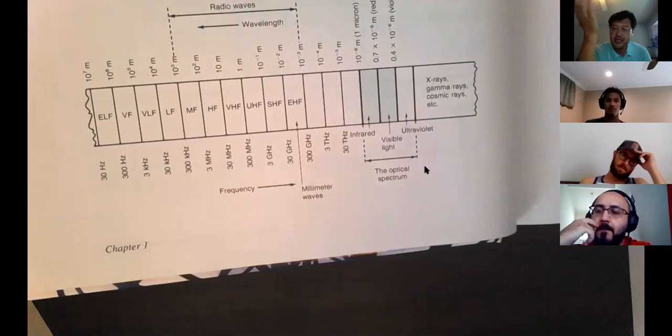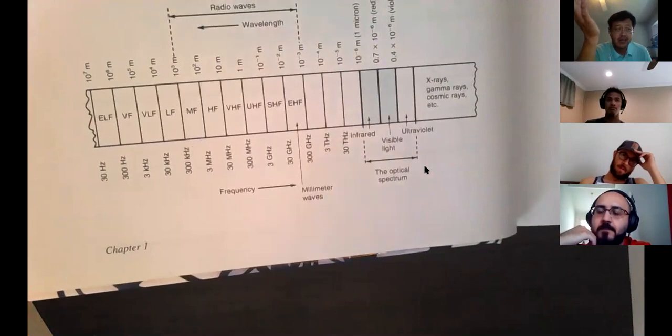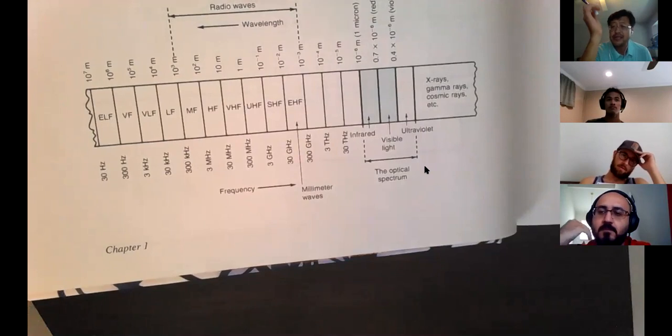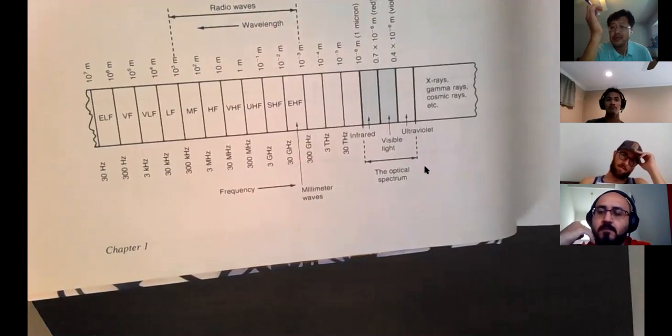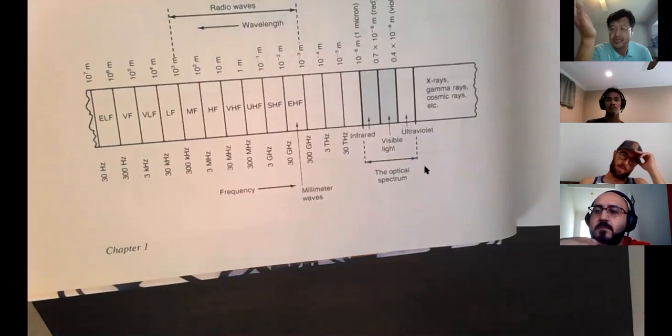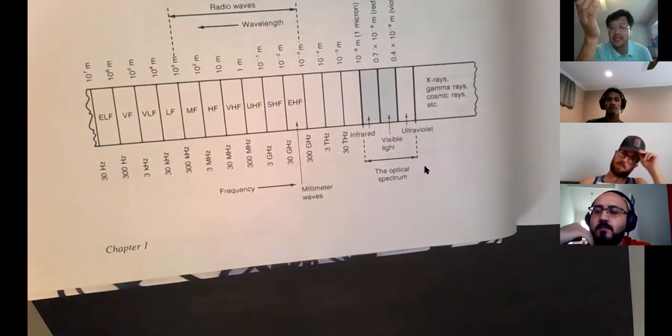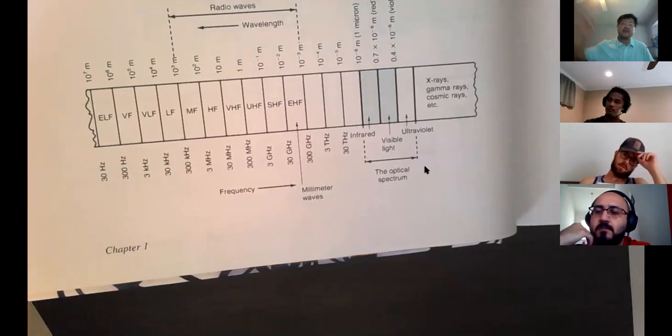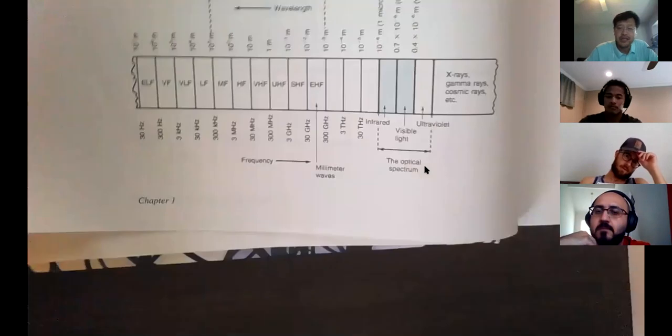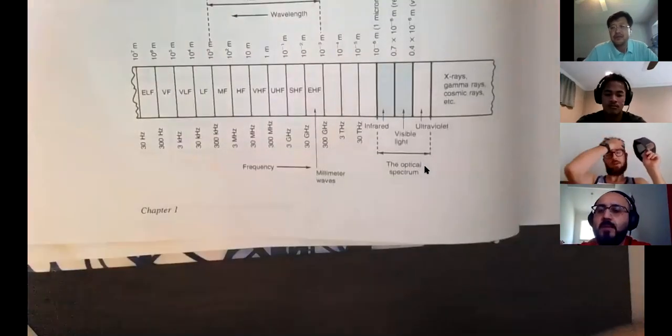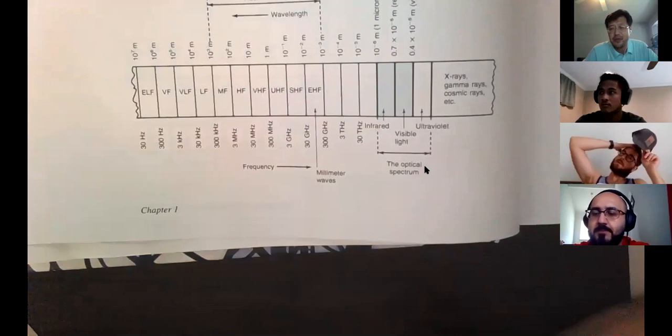For example, in Shenzhen with 4G, 100 antennas is enough. But if you deploy 5G millimeter wave, you may need 1,000 antennas around Shenzhen to make it work, because they don't travel a mile or half a mile as 4G does. They only travel maybe 100 to 200 yards. So you have to have one every 200 or 300 yards. You have to put in more density, more antennas.